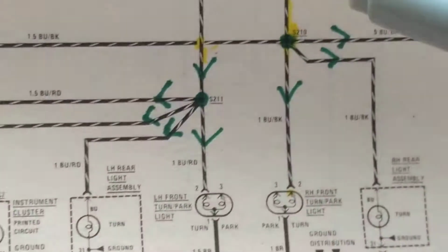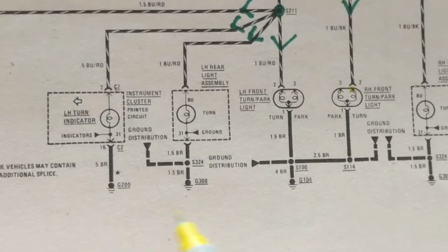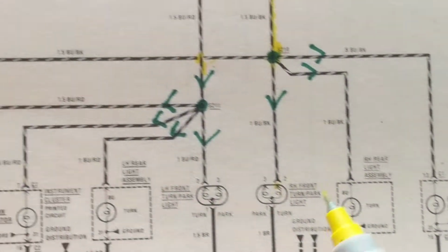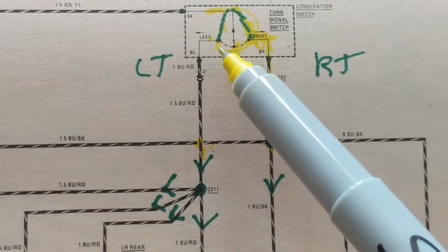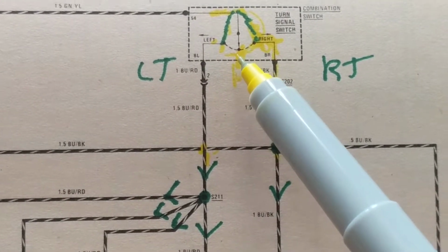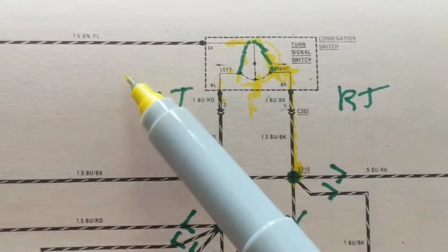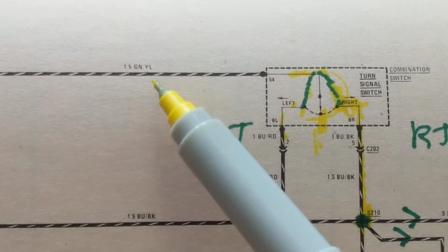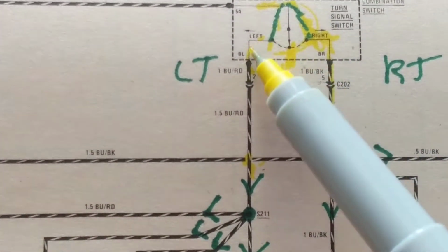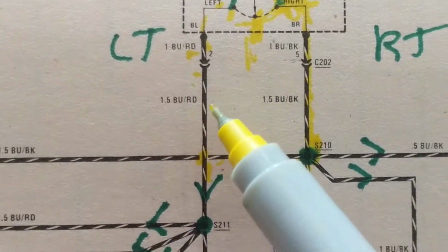What about the left? So looking at the schematic, this deals with left. This deals with right. Remember, now we flip the switch in the other position because we want left. So when we have left, we have current flowing from the battery, which is not shown here, right? Green, yellow wire flowing through here, through a blue-red wire.